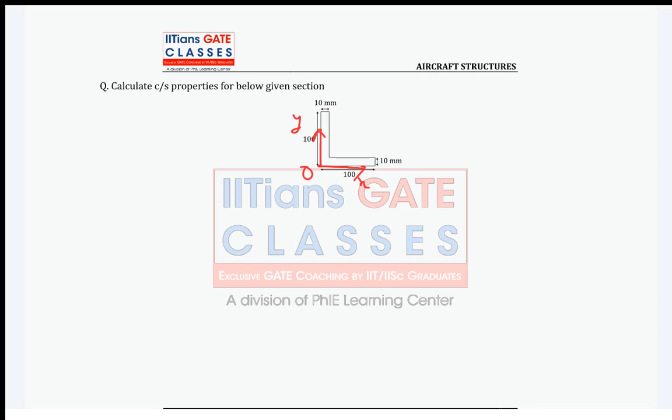For the summation formula, we have to divide this section into multiple parts, to make multiple symmetric sections, right? So you can divide this L section in whichever way you want. How can you divide? Either like this or like this, so you will have two rectangular sections. Which way do you want? Like this. So when you divide this L section into rectangular sections like this, what will be this dimension, guys? It will become 90.